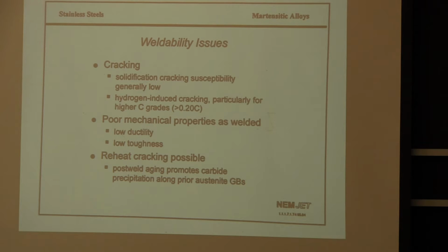Also, because of the martensitic structure, you get poor mechanical properties as welded: low ductility, low toughness. The problem with that is you can have catastrophic brittle failure of your component, and so you typically need to do some post-weld stress relief to reduce that.